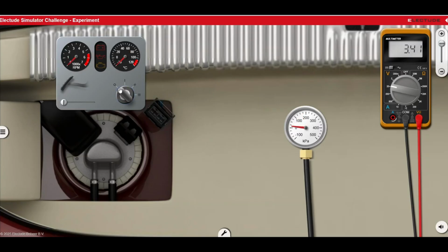That's what happened. That's why the car is not even starting now. Now, if I were to connect this and switch on the key again without cranking, without starting the engine, the pressure is going to go up. You heard that. That's the prime. Now, when you start, the vehicle runs immediately. You can see the RPMs here. If I disconnected the pump, the engine dies and the pressure falls.